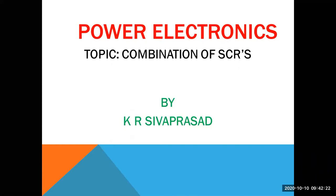For example, if you consider a 10 kilovolt SCR, for simple understanding, if you consider a 10 volts SCR, then 10 SCRs can be combined in series to reach our required voltage rating, because in series connection, all the SCR voltages will be adding.